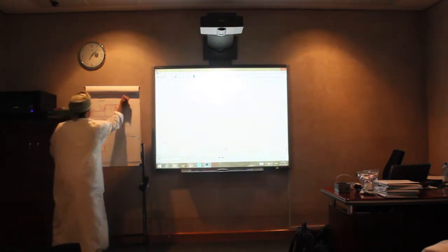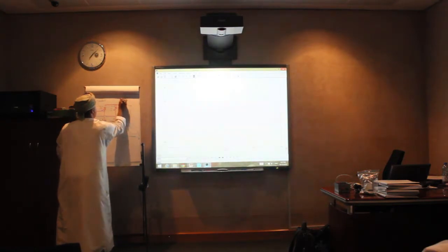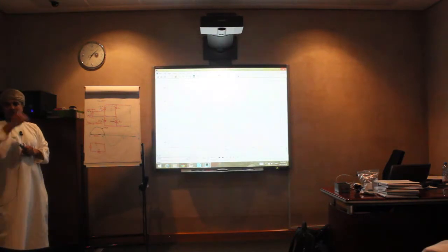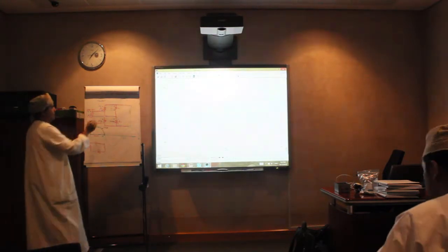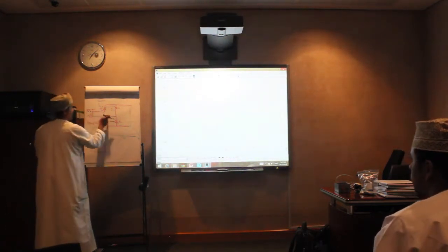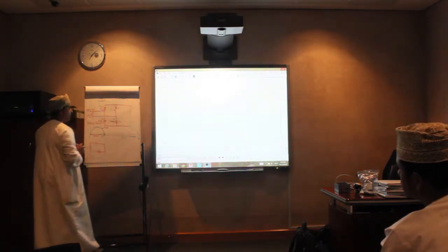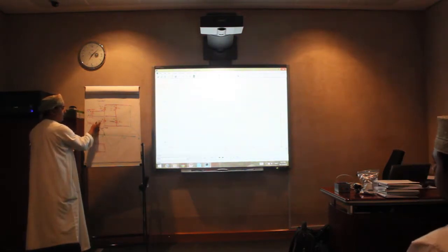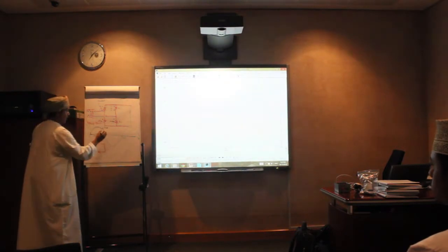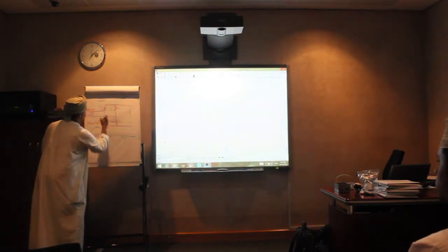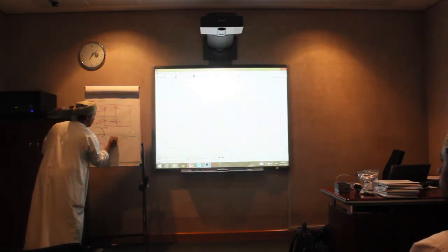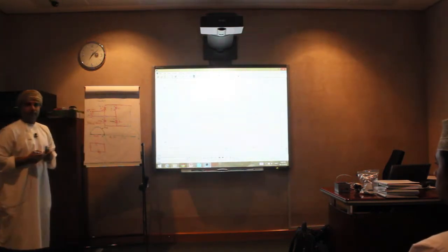Remember the direction of the current in the diode is in this direction. So it conducts only in one direction like that. It doesn't conduct in the opposite direction. So that means this one will conduct, and that one will turn off because it's in reverse bias, while this is in forward bias. So it will allow the current to pass through this diode, and it will come back through this diode. So it will not conduct on that one. So in the second half cycle, D2 and D4 will conduct, right?